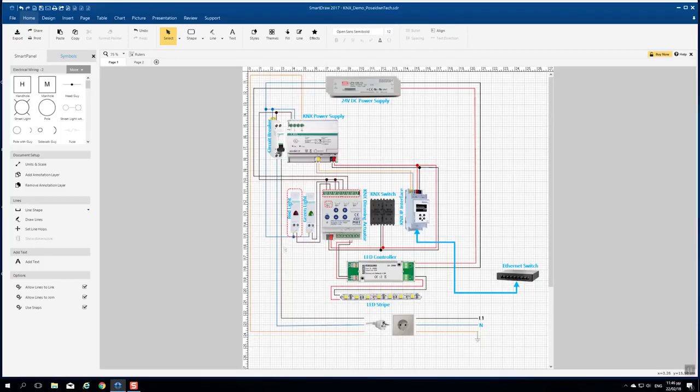So, in channel A of this actuator we will connect the line from the circuit breaker and the red light. Of course, the red light, in order to operate, will also need the neutral from the circuit breaker. Channel B, like channel A, will follow the same connection in order to control the green light.